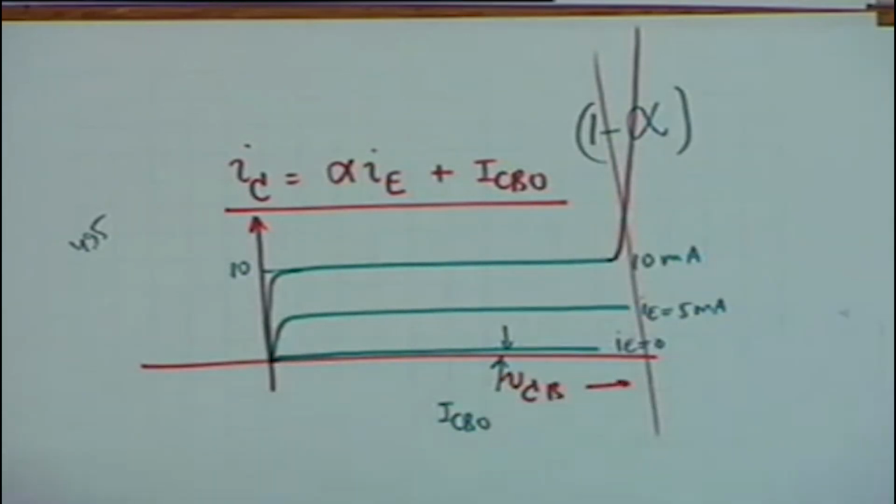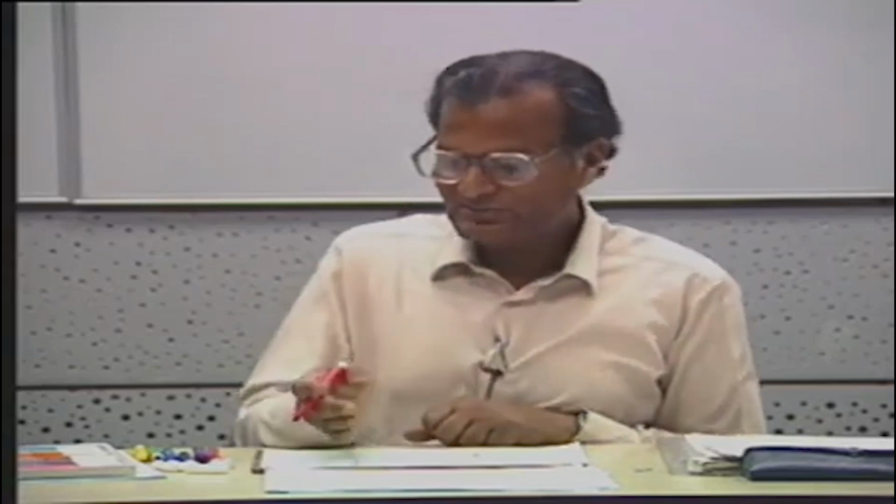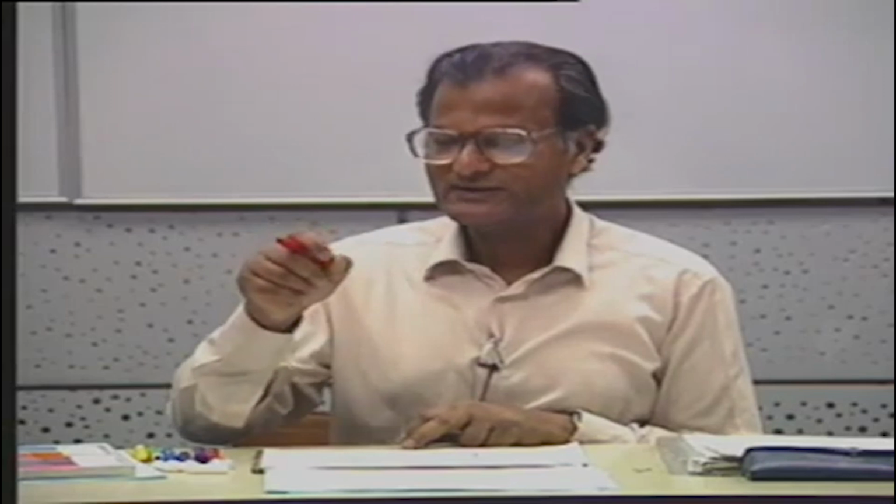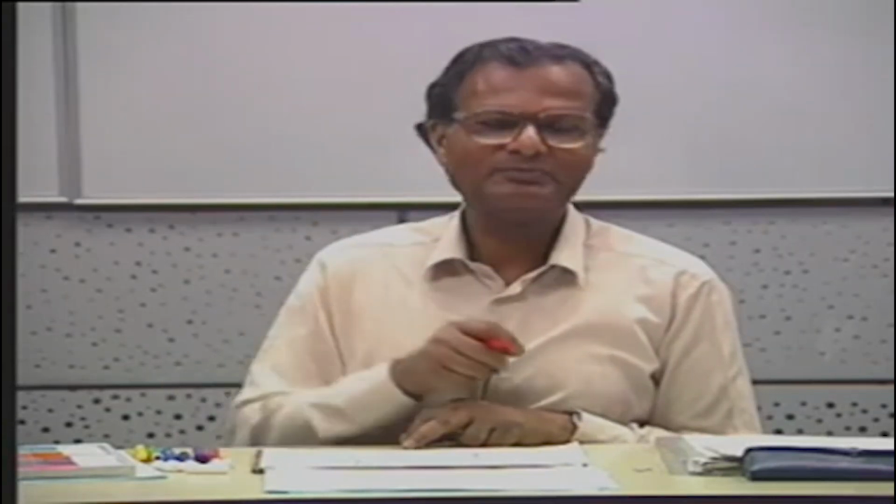Every transistor has a certain power dissipation capability, and no transistor is fabricated to dissipate the Zener power. No transistor, Zener only with diodes. This operation may be irreversible, and therefore one never goes beyond that region. So every transistor comes from the manufacturers with a spec of P max, that is, you must not dissipate more than this amount of power.